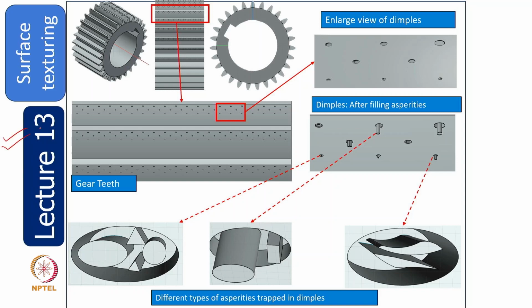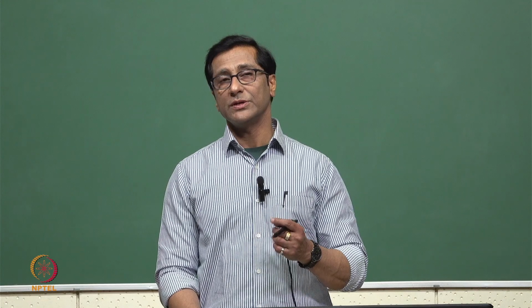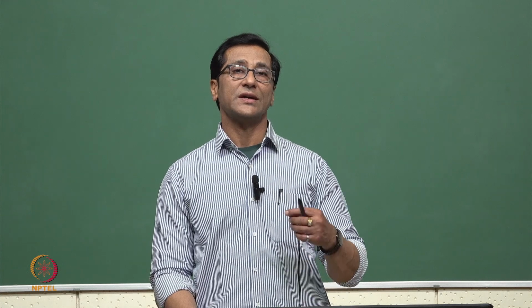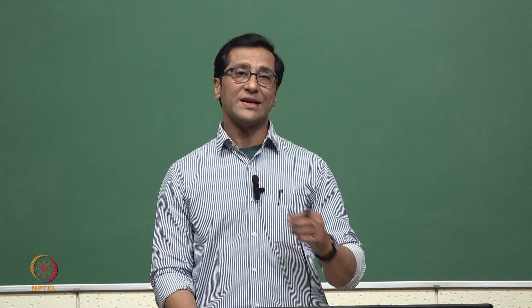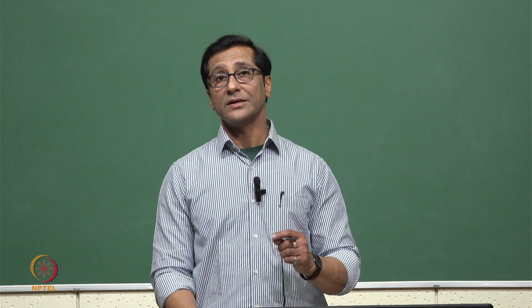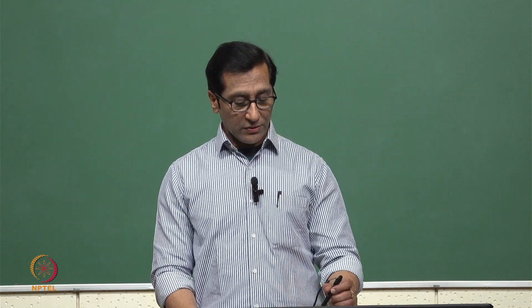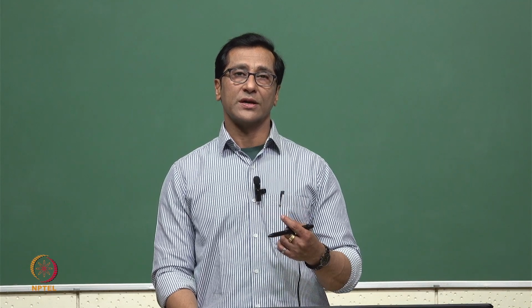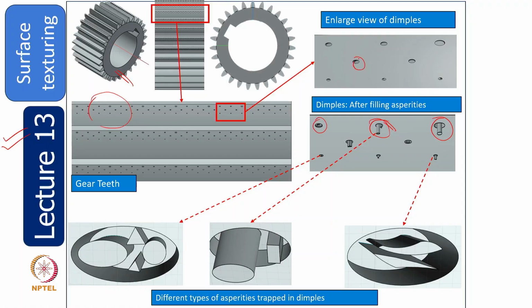We covered in lecture 13 some other types of gears, and we said, why not do surface texturing of various depths and various dimensions? Why do we do that? Reason being, wherever there is wear, debris will keep coming out of the surface. Now if that debris is not cleaned and remains at the interface, it will enhance the wear rate. So to keep the wear rate lower or minimum, that debris needs to be dumped into this kind of texture, which is like a dustbin already available, and the debris will get dumped into this. Not only this, we also say that this kind of texturing is required to retain the lubricant, particularly whenever there is movement and lubricant is not sufficient. If that lubricant is already available in these kinds of reservoirs, then it will really reduce the friction and wear. So this is why we say surface texturing is also important, and this was covered in lecture 13.